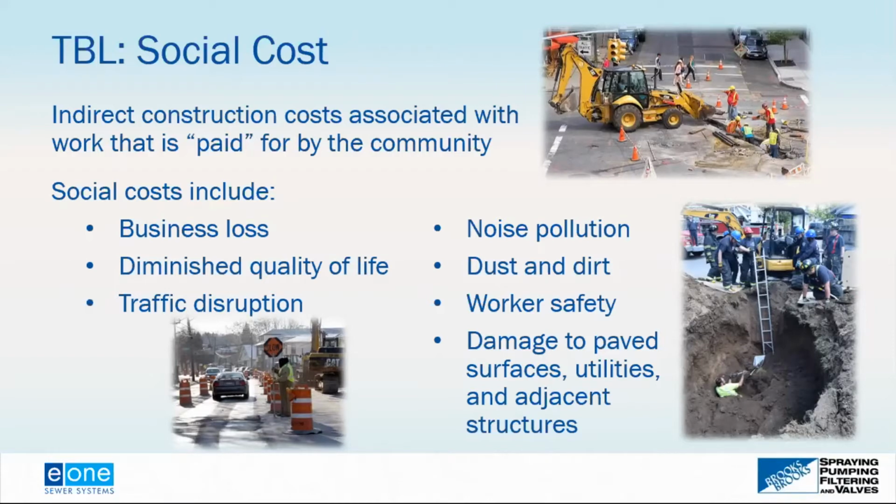Anyone involved in the horizontal infrastructure business, such as sewer systems, knows that sometimes it has to go over a couple construction cycles. You dig the trench, you install the pipe, you backfill the trench, you pave, and then you come back next season to address that trench again because where the trench was, the pavement settled. So you do have to worry about that damage and those follow-up activities. That's what's impacting the homeowners, the businesses, the people around there. When you put in the sewer system, you're trying to solve a problem. You certainly don't want to solve a problem that creates more problems for the community.